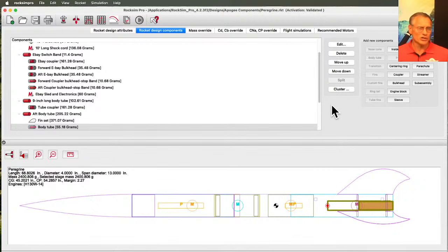Now we want to launch it, and we want to find out, is it taking off fast enough? Why do we want to know that? Because our rockets are not guided. It means the rocket motor doesn't gimbal. It doesn't move around like a motorboat, where the motor can swing back and forth. That's called a gimbal, and that changes the direction of the rocket. Our rockets are unguided. They can't change the direction of the thrust. Because of that, the only thing that's stabilizing the rocket is the fins, and the fins need air flowing over them to create forces.